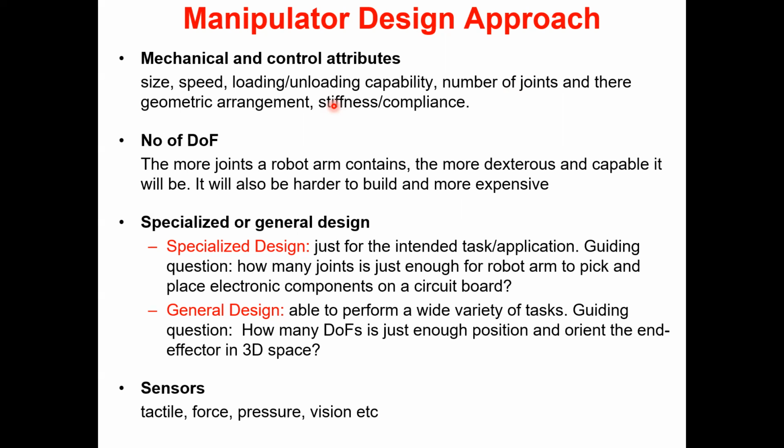In that case, you cannot have this stiffness at all times, right? Sometimes there are cases where you need to have high stiffness, but other times when they work with humans, they need to have compliance. So you accommodate the external forces, and temporarily you accommodate errors, right, in order to minimize the contact force. When the robot is in contact with something, there's a contact force, and if that force is too much, you have to reduce that contact force.